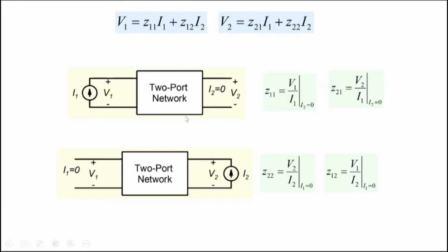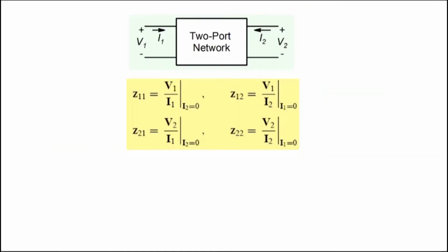So any circuit, any unknown device, a transistor or something else that is there, suppose somebody has invented a new transistor, and a model for it has not been built yet, but you could take that particular transistor and experimentally measure Z11, Z21, Z22, Z12, and thereby you have a representation of the transistor. And that representation you could deploy anywhere in your circuit and determine what the circuit performance is going to be here.